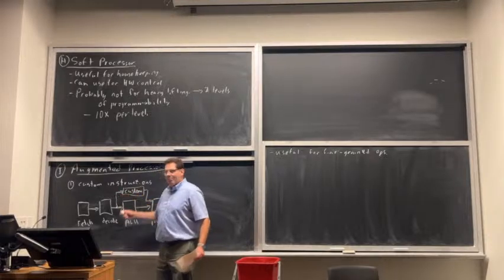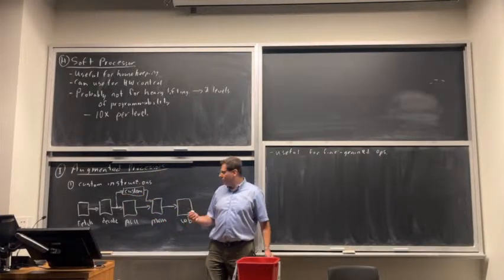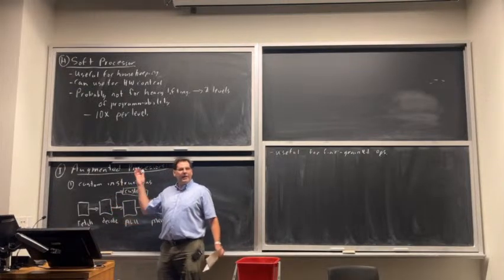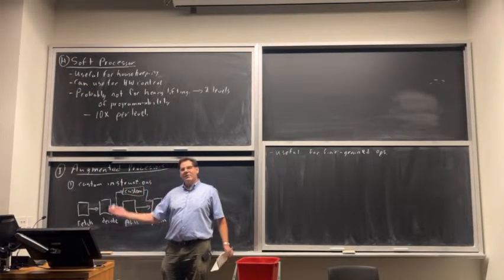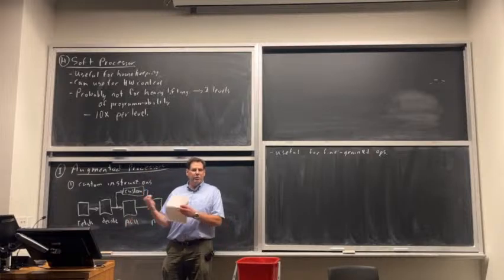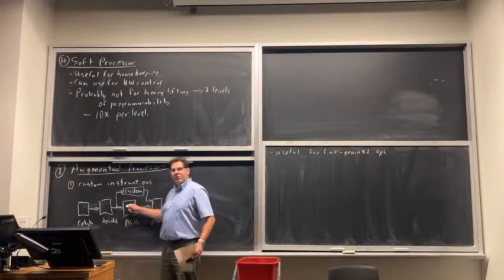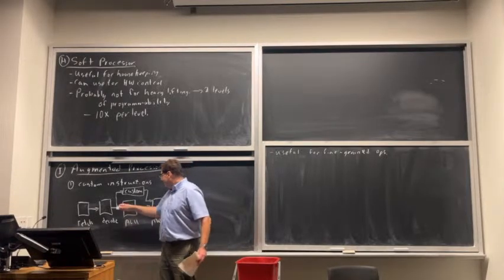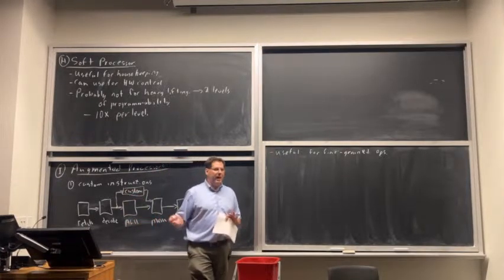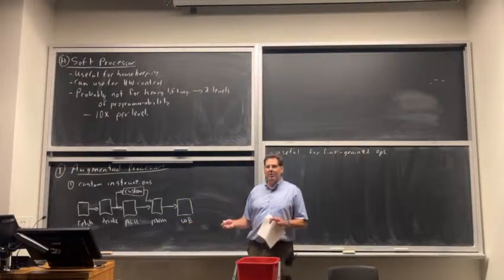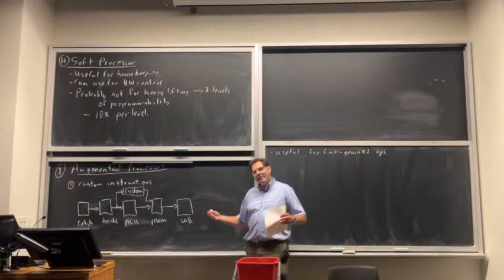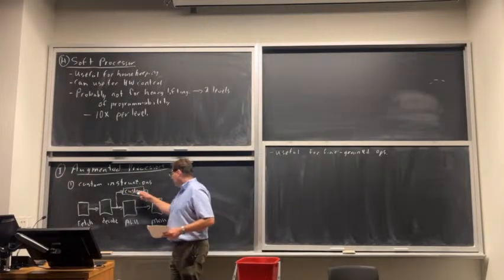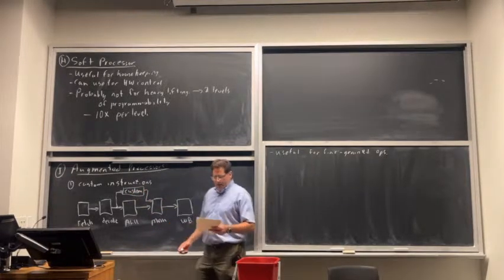Also, how many operands did it get? It's just hooked up to the regular operand broadcast buses. So a classic processor has 2 input operands to the execute stage, and it produces 1 output operand. This is basically hooked into those data paths. So that limits how much input you can get to it as well. I can only send it 2 pieces of data, and if it takes longer than the cycle, it stalls my pipeline.